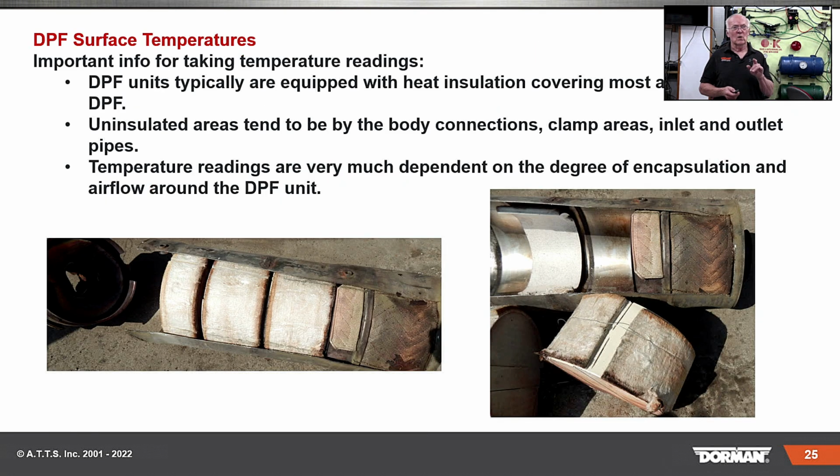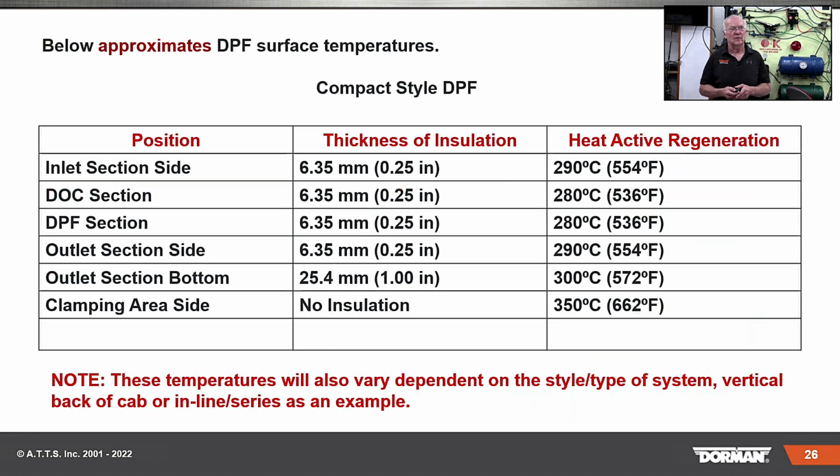Now, when you take temperature readings, one of the things you want to be aware of: I cut this unit apart, I believe a month or two ago. The only reason I cut it apart was that you need to be aware of what you don't see internally. There's insulation wrapped around these catalysts, but there are areas where you don't have any insulation. If you take your pyrometer or imaging camera, you have to be careful, or at least realize you have areas like that in there.